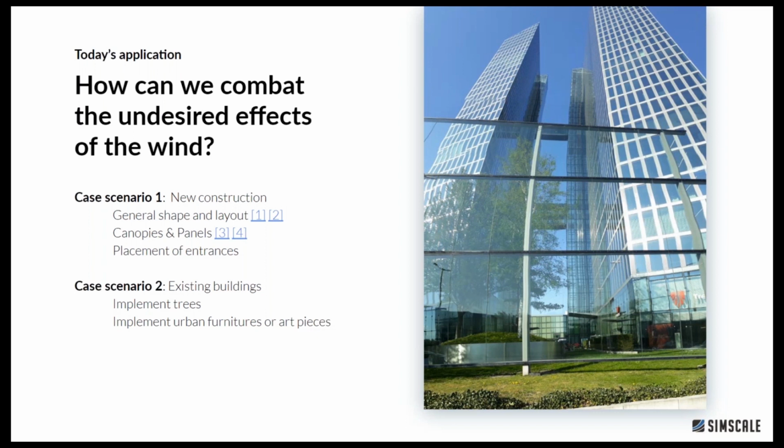Between these two towers, we can see there could be a potential issue for the wind to gust in between them, and they've implemented a nice wind-breaking panel in the middle, just to prevent discomfort for pedestrians and passersby. This also acts as a noise barrier because there's a highway right behind it. I just found it interesting that everywhere you can see some method that has been implemented to mitigate these effects.